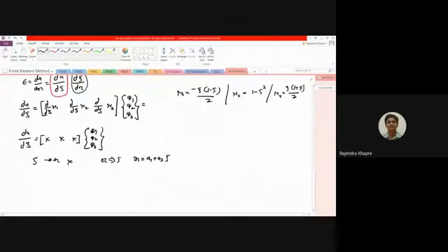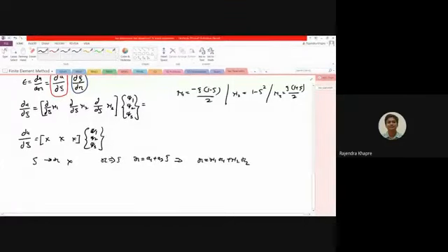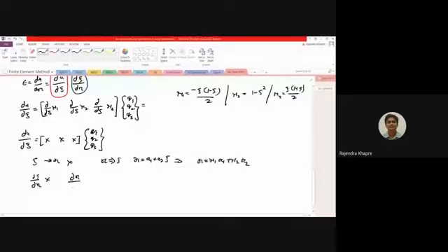So x is equal to N1 x1 plus N2 x2. What we are interested in is del xi by del x, because this is required over here. We cannot go for del xi by del x directly, but we can go for del x by del xi.